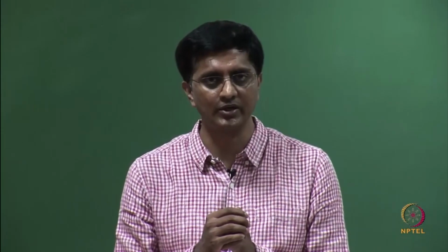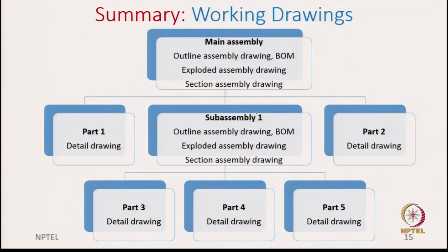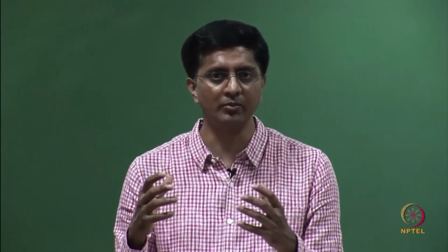So, I think this gives us an idea about what a working drawing is. In this course, we will be focusing more on the sectioned assembly for practicing purposes, but as a practicing engineer, we need all this set to go to the fabricator or a contractor, so that they need not come back to you for small details. Though they can call you anytime, your drawings should be a standalone piece, which means they should be able to communicate each and every detail of your design without people contacting the designer again.